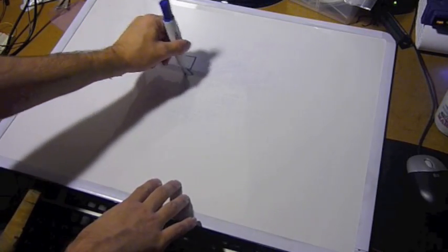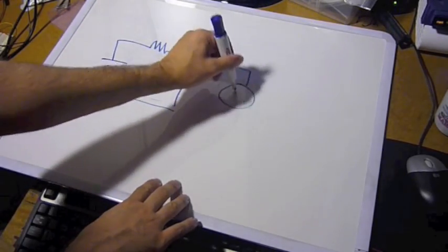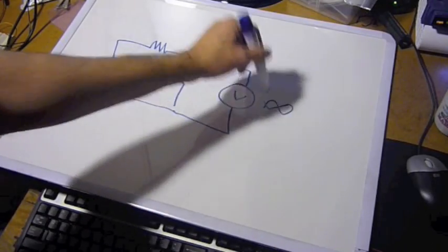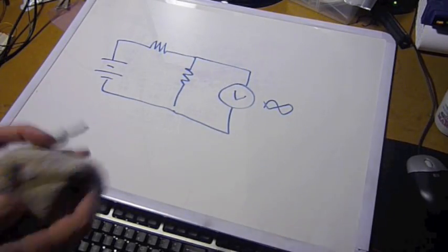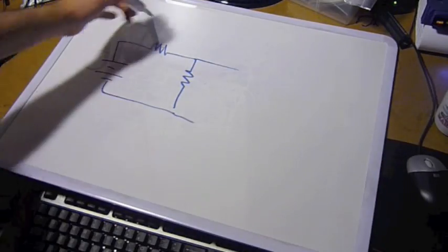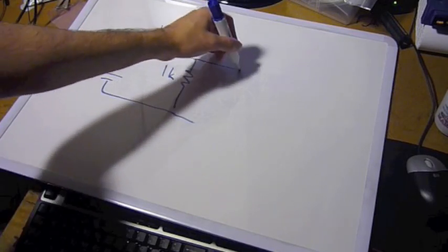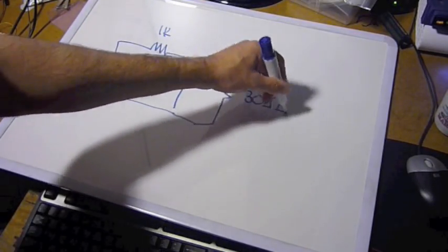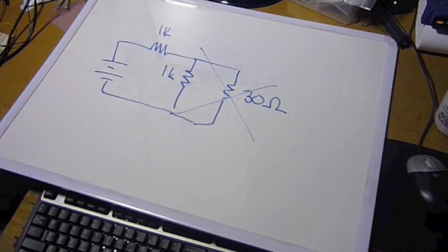Think back to a voltmeter. You may recall that an ideal voltmeter has infinite resistance. That's because we don't want to draw current from our circuit, affecting the reading at a particular node. In the same way, the op amp has high input impedance so as not to disturb the input signal. We'll talk more on this later.